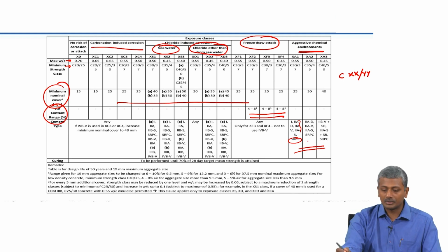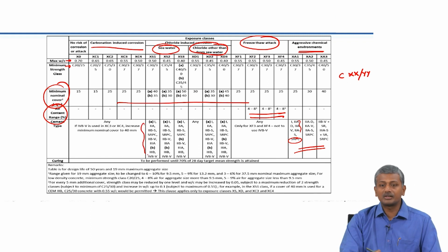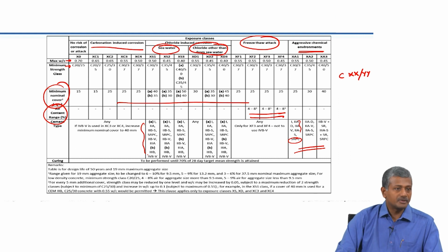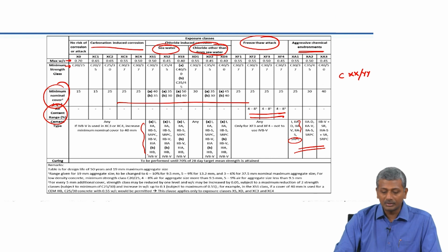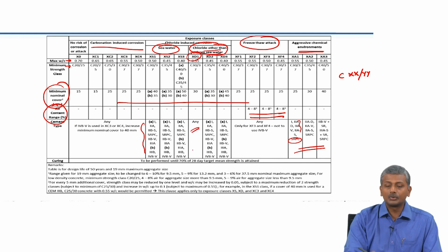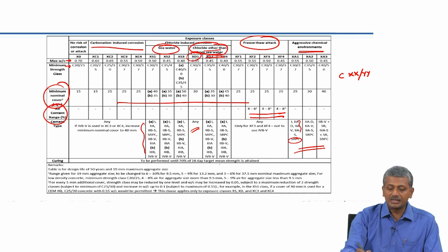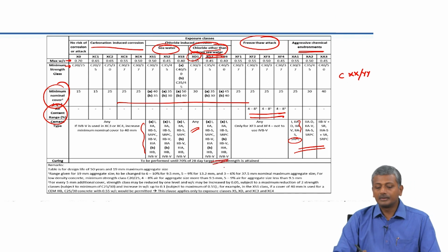So, sulphate resistant Portland cement is used, as well as composite cement combinations that we talked about in the cement composition chapter. Okay. So, again here with chlorides, they generally prescribe cements which are rich in slag or fly ash. Okay. Most of these cements are slag based cements which are clearly specified for the seawater. Again, for the exposure classes for chloride other than seawater, for the lowest exposure class they ask you to use any cement, but when you go for a higher level of exposure, XD2 and XD3, there are requirements for slag based or fly ash based cements.